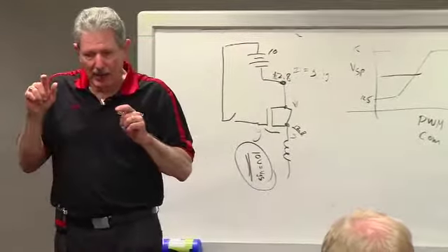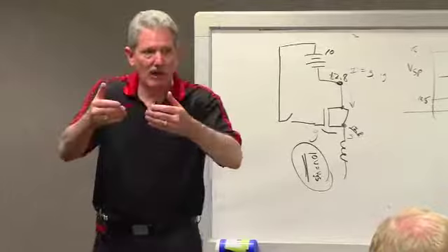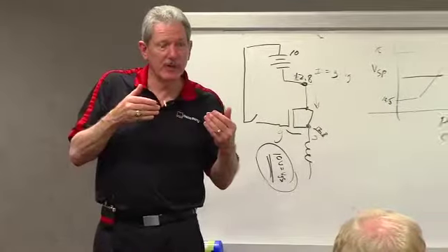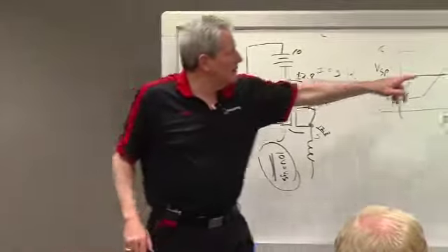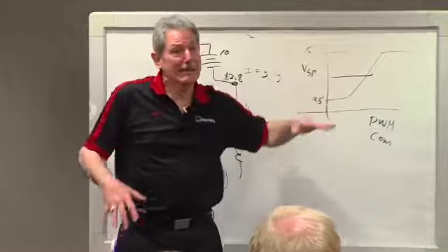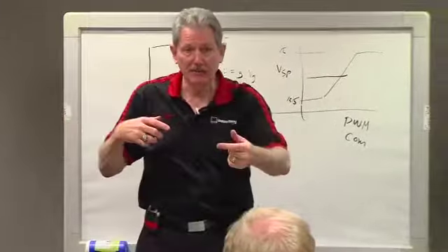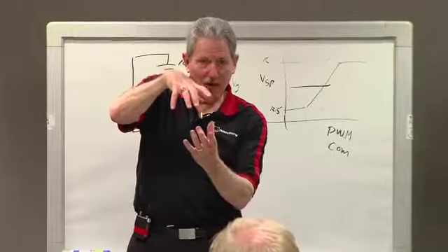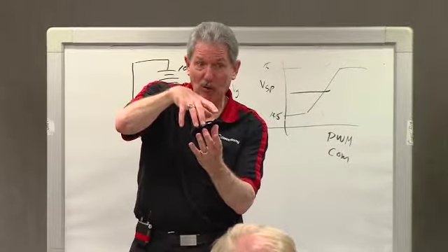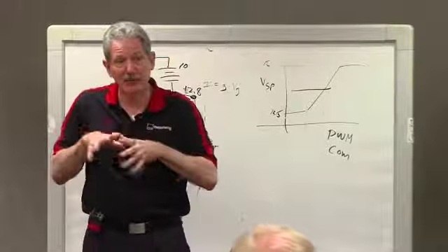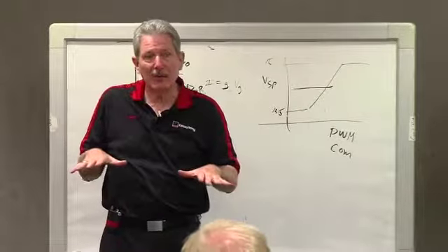Okay? Now I take my foot off of the accelerator to go to the brake, shoot it to 15.5, because it'll never get to 15.5. The alternator will go to full field. It will take all that energy that you're telling it to pull from the engine, and it'll suck it from the engine, and it'll be a dynamic brake.